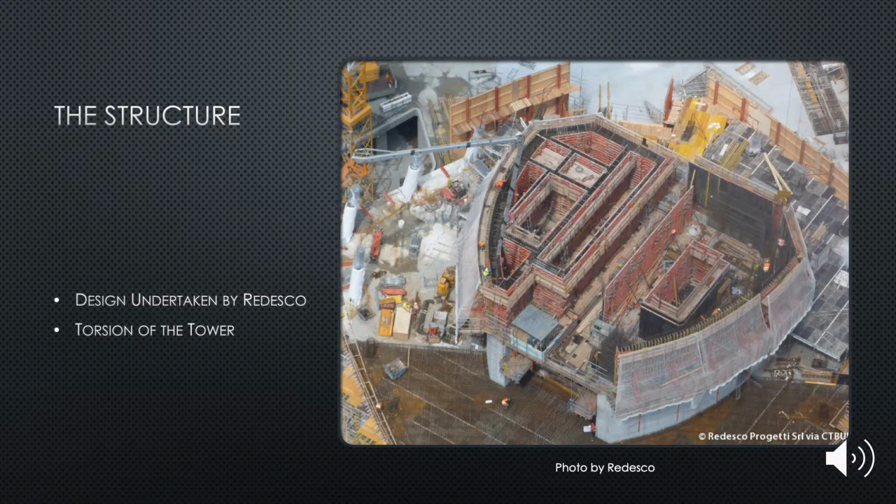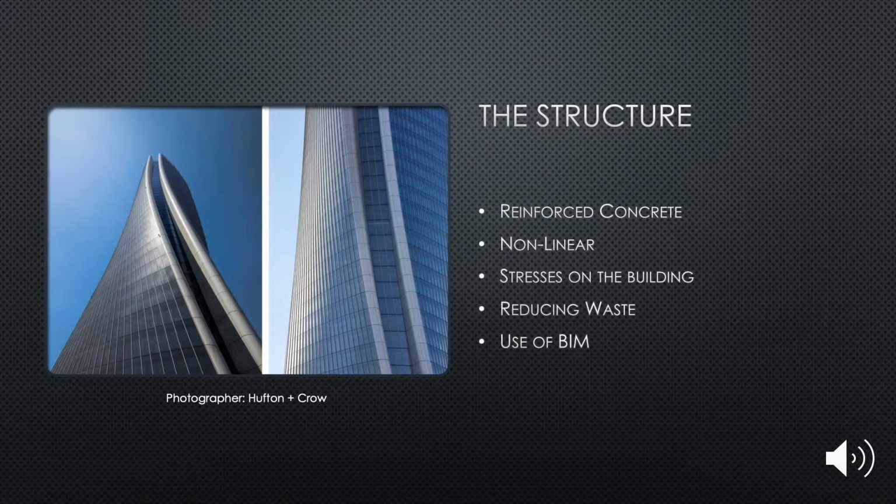Redesco carried out a thorough evaluation of the structural alternatives once the layout of the structural members had been determined. This evaluation indicated that reinforced concrete would provide the best benefit-cost ratio. Whilst using reinforced concrete is more efficient, it also makes the structural elements much more complex to design and calculate than if steel were to be used, for example.